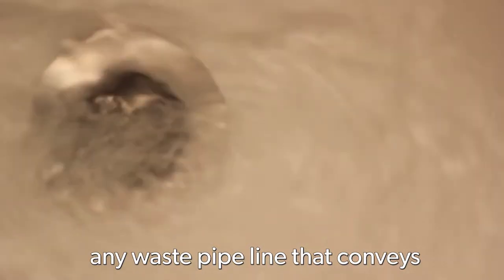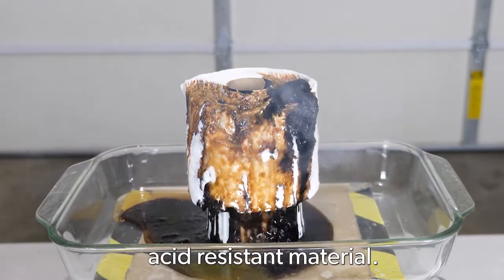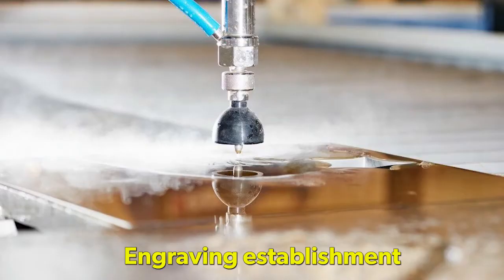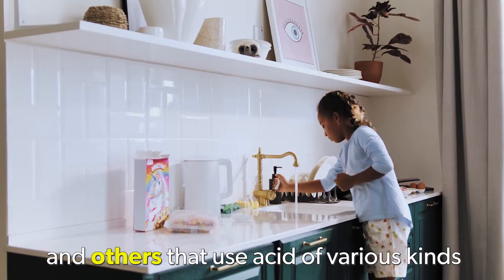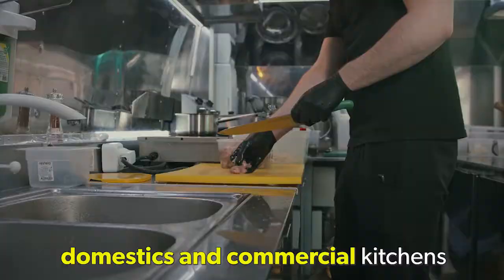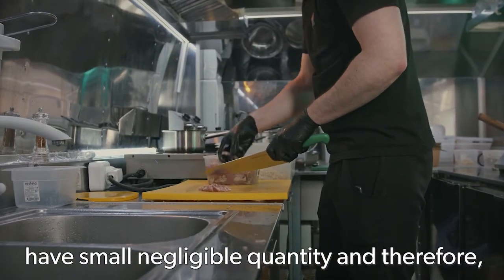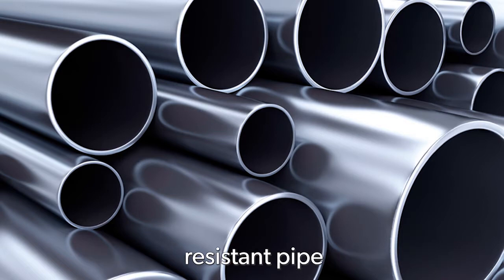Any waste pipeline that conveys a large amount of acid must specify acid-resistant material, examples of which are fixtures serving chemical laboratories, plating, engraving establishments, and others that use acid of various kinds. However, waste coming from domestic and commercial kitchens that sometimes contain acid of different kinds have small negligible quantity and therefore does not require the use of an acid-resistant pipe.